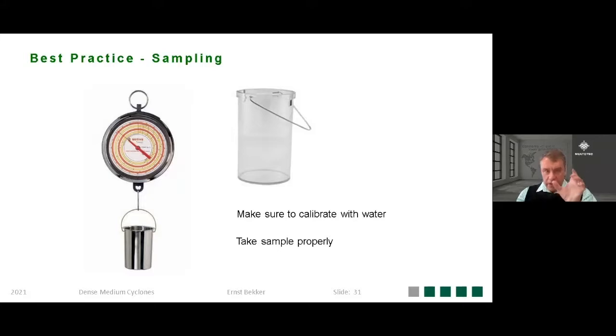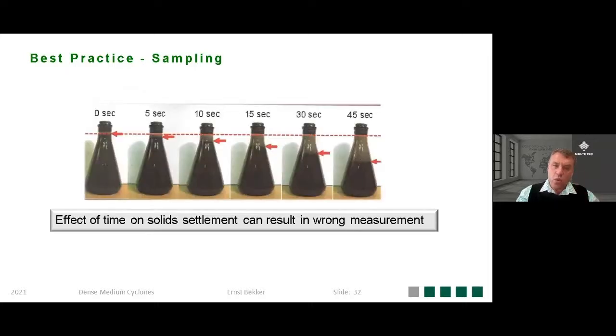In some cases, you then walk over and put it onto the scale. If that is the type of activity that you're doing, you've got a problem, because while you're walking, the media starts to settle out. By the time you've removed your hand to drain that to the correct level, you're only draining off water, and there goes the accuracy. That's especially relevant when you're calibrating your densitometers. You take the sample, remove your fingers, drain it, close it again, and move on to the scale.